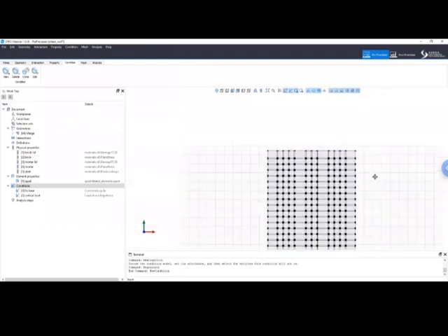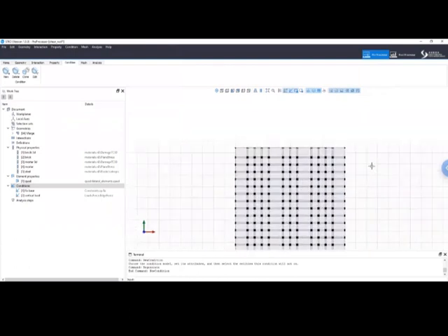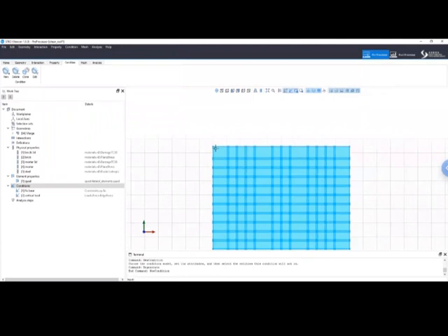Okay. Now the next boundary condition that we need to assign is a boundary condition that fixes the rotation of the top beam. So the beam cannot rotate, can only move as a shear wall. And how do we do this? We need to create an equal DOF constraint. But before doing this, we need an interaction.